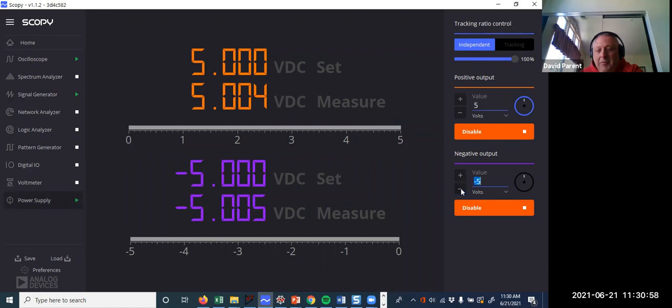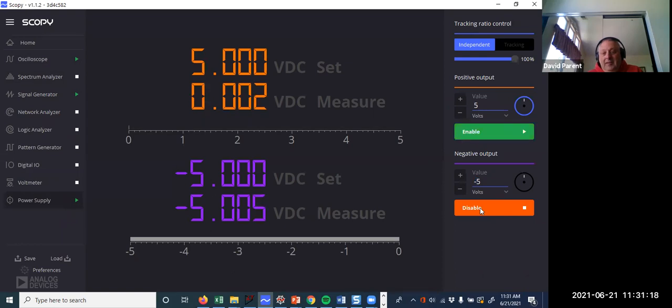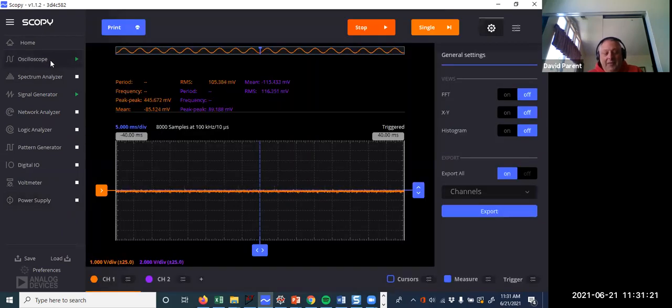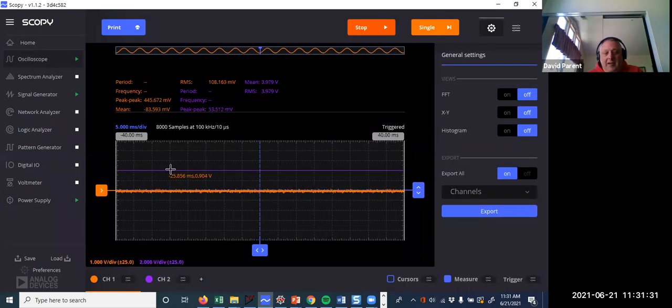And I'm going to set my power supplies back to where you'd start. And notice it's not changing. The output isn't changing because the noise is just too small to get it to switch states. So if you see it not changing, of course, something could be wrong, disconnected or whatever. But what does not having the power supplies look like? Just kind of everything zero, right? But even when I enable the power supplies, it's not enough to get this going back and forth.